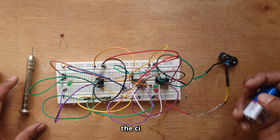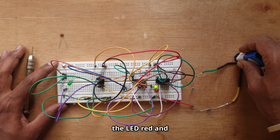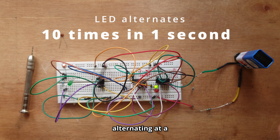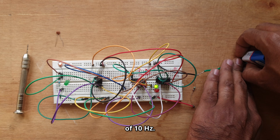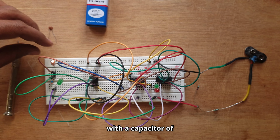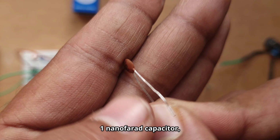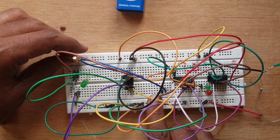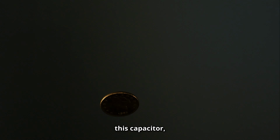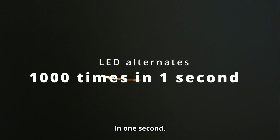Now let's power the circuit. Once we power the circuit, we can see that the red and green LEDs keep alternating at a frequency of approximately 10 Hz. Now let's try with a capacitor of even lower capacitance. This is a 1 nanofarad capacitor, in other words 0.001 microfarad capacitor. Once we use this capacitor, it needs to alternate the LEDs at around 1000 times in 1 second.